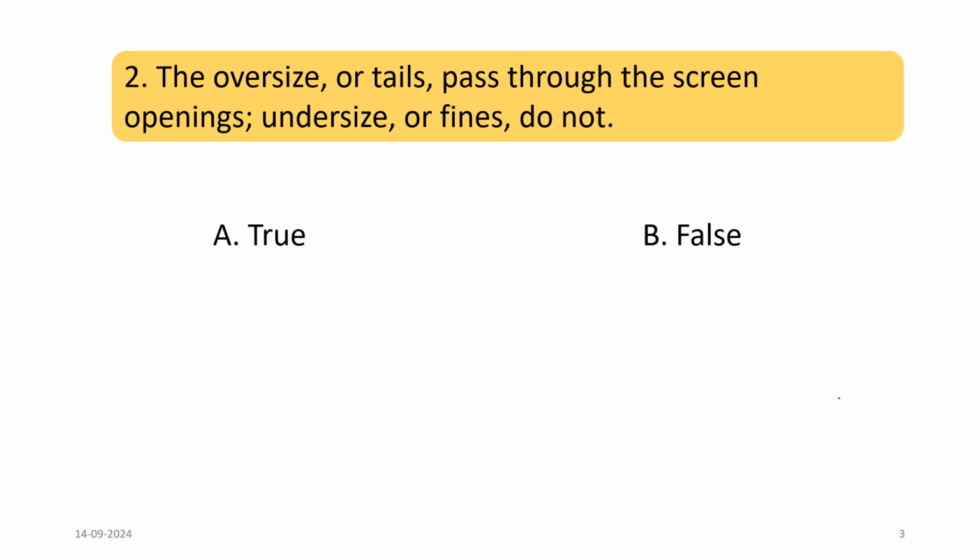True. No, it is false, because I have said oversized particles pass through. Oversized particles don't pass. Undersized particles pass through, so it is the opposite one. Undersized or fines pass through the screen openings, and oversized tails do not. So this is false.